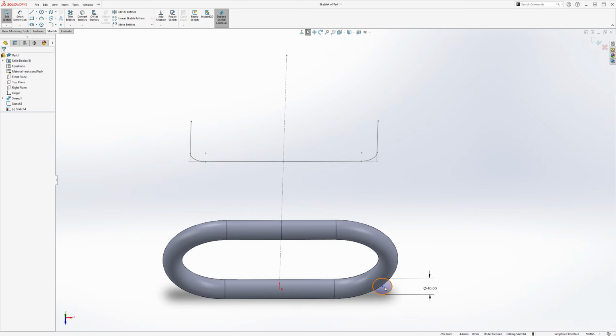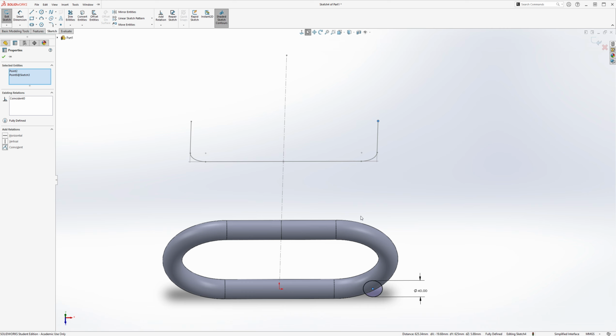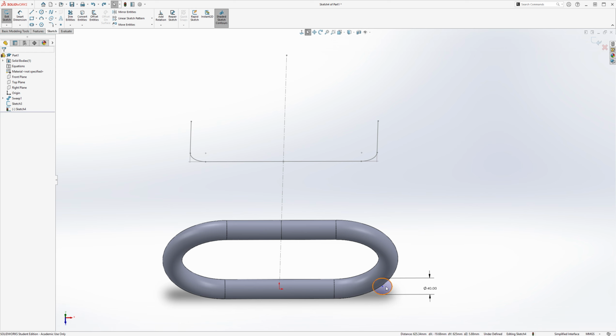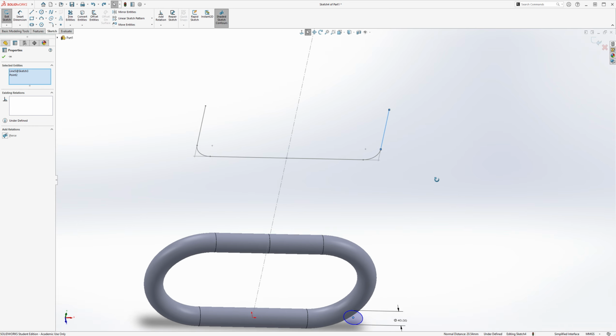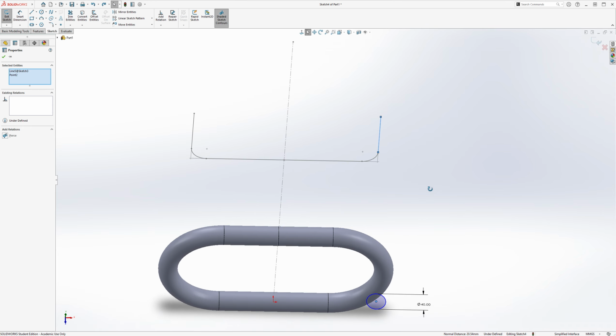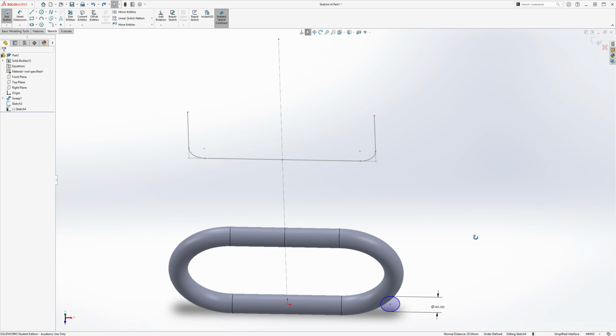And then I'm going to make this, control, center point, control, this point. I guess we'll make it coincident. Oh, actually, no. I want to make this point and this line pierce. No intersection found for the pierce point.